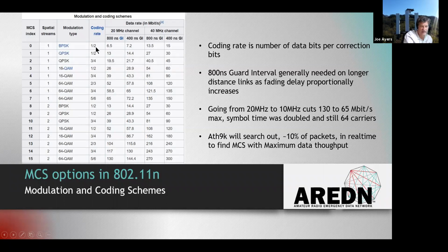This says that there's 1 bit of data and 1 bit of error coding, so half of the bits are to help recover the data. Here it says we have 3 data bits and 1 coding bit. The fourth one is forward error correction coding.